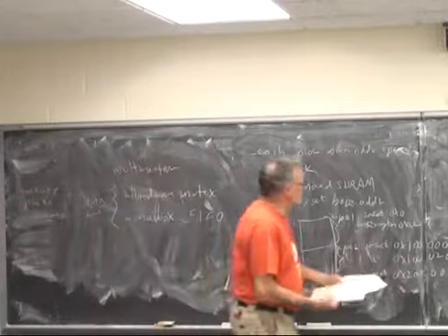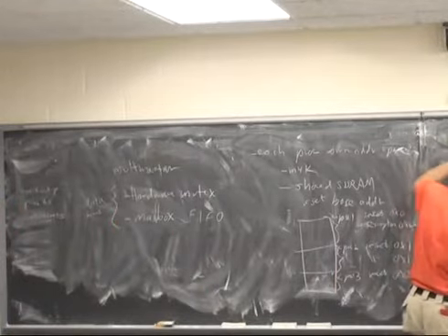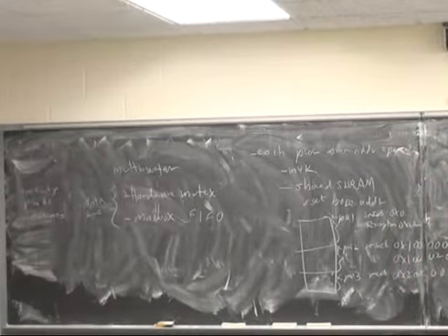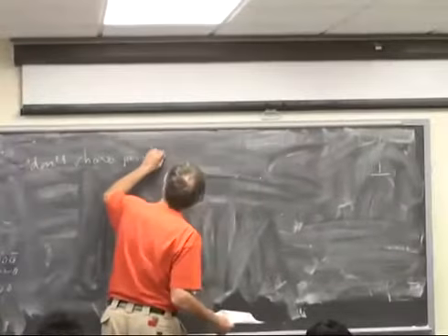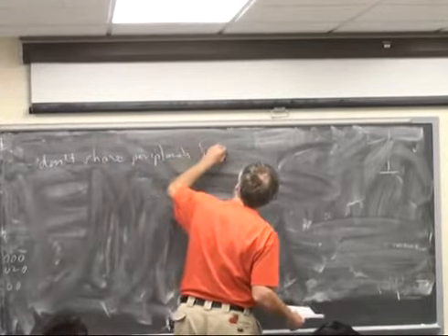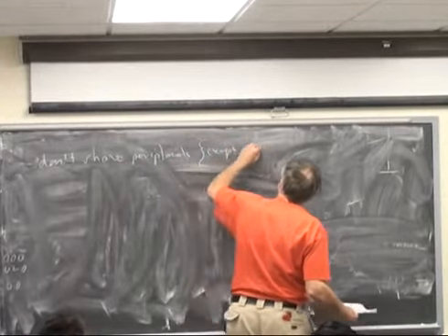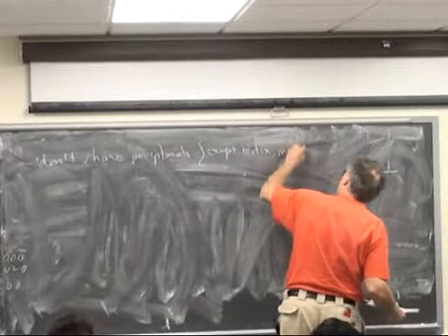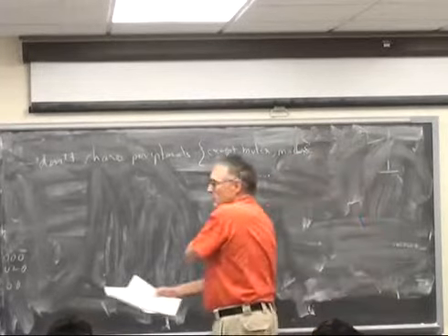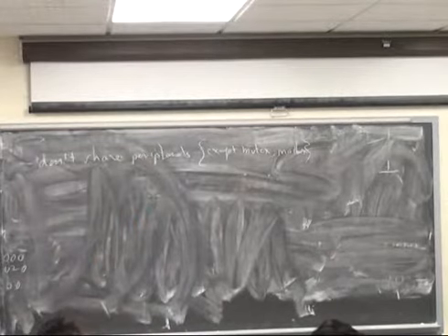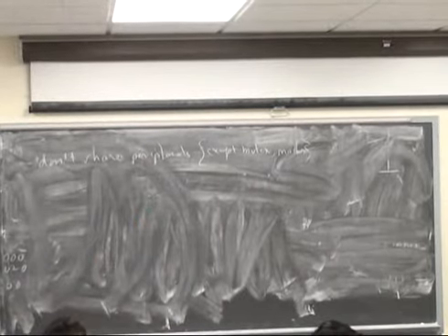Another rule is don't share peripherals, except for mutex and mailbox. In other words, don't hook a timer to both CPUs. I think it will allow you to do that, but don't do it.